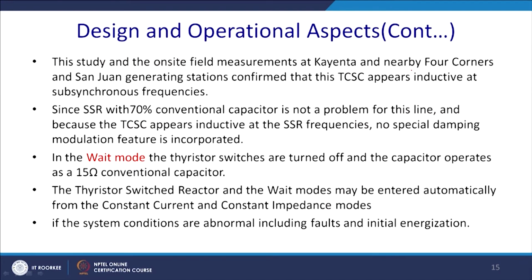the on-site field measurement of the Kayenta and the nearby Four Corners generating station confirmed that this TCSC appears inductive in the subsynchronous frequencies. So, it has a capability to damp out the subsynchronous oscillations. Since SSR with 70% conventional capacitor is not a problem for this line, and because this TCSC appears inductive at the SSR frequencies, no special damping modulation features are incorporated. So, this is inherent, that is, it has SSR damping features.